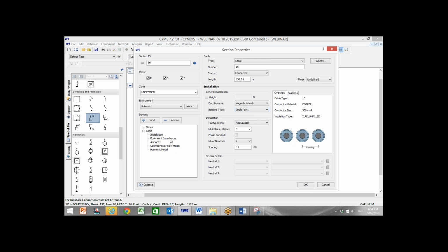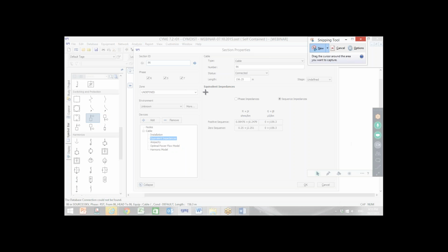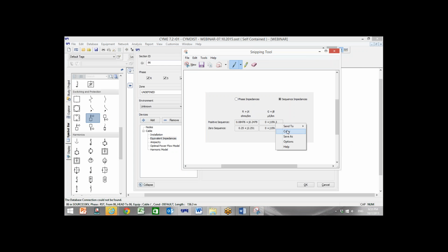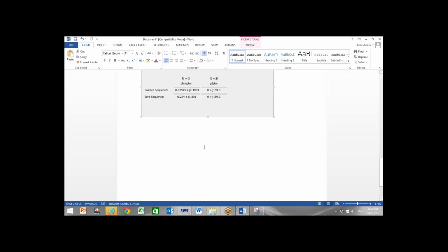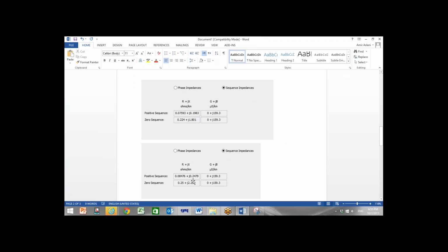Definitely it should. If I go to impedance, now I go to magnetic duct because the equivalent will be changed. I put the values here. So you can see the reactance change. And something else important, resistance change. Why resistance change? Because of proximity effect.